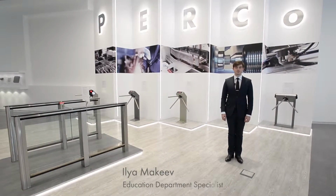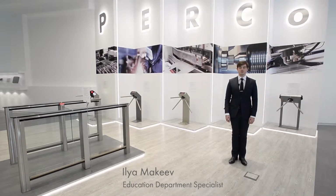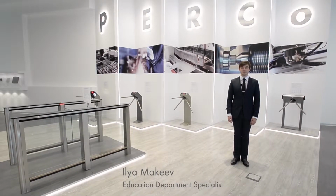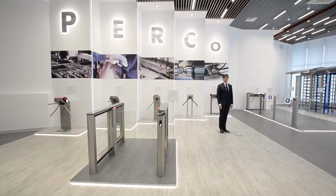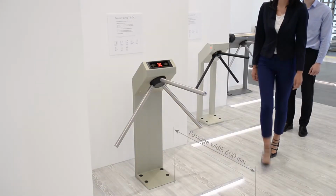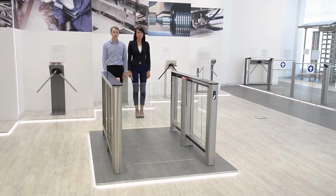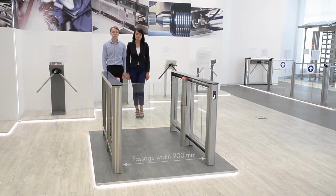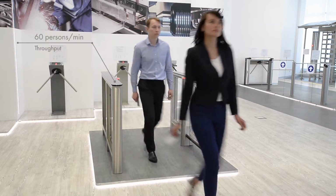Throughput and passage width are important factors when choosing a turnstile. The throughput is calculated according to peak load at the guard desk. The passage width affects convenience and comfort. For instance, tripod has a passage width of 500 to 600 millimeters and throughput 30 persons per minute. The speed gate has a passage width of 650 to 900 millimeters depending on the panel size and throughput 60 persons per minute.